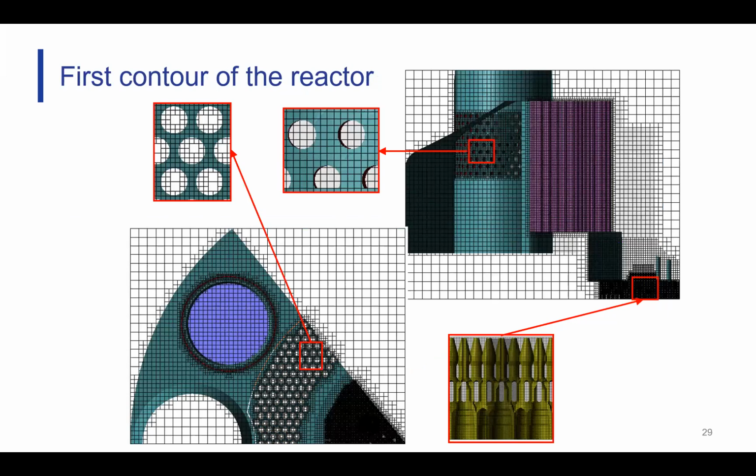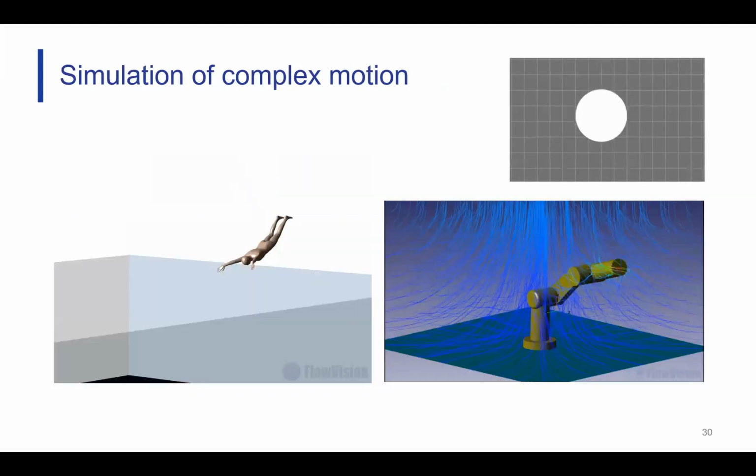Similarly with adaptations and grid refinement, you can specify regions to be refined by selecting objects, selecting boundary conditions, or you can apply the refinement in a fixed volume, or maybe to occur based on the results of the calculation. Again, whatever you feed FlowVision, FlowVision will automatically adapt the mesh based on the conditions that you're specifying.